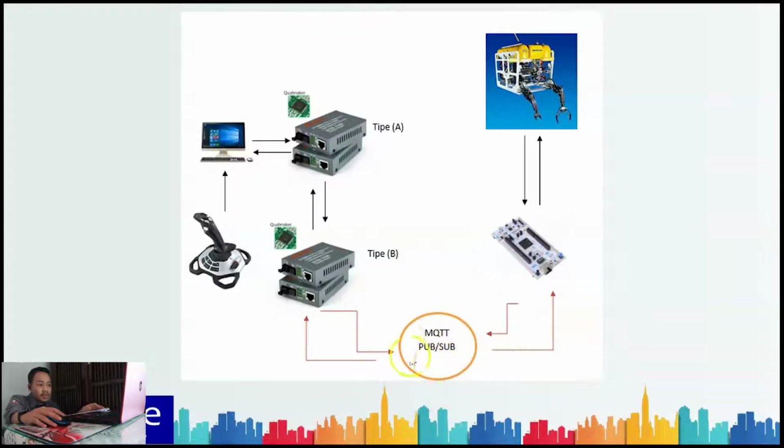After we program and connect to MQTT, the red LED on the STM32 can turn on or off by sending a publish message on MQTT, on or off. If I send on, the LED on the STM turns on, but if I send the message off, the red light on the STM will be off.